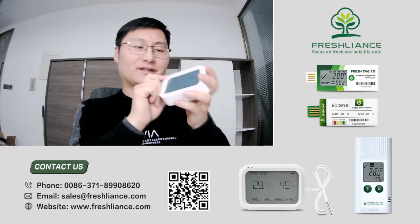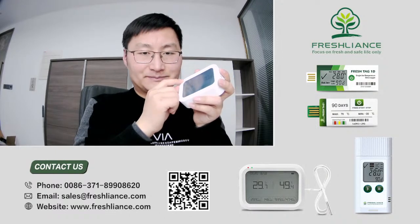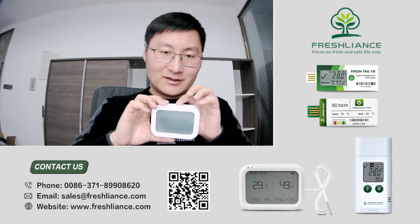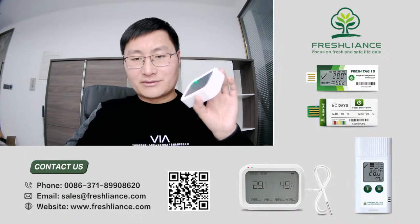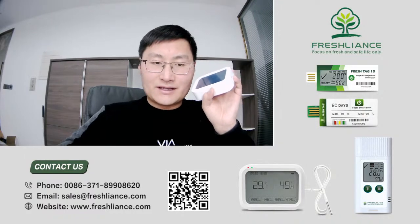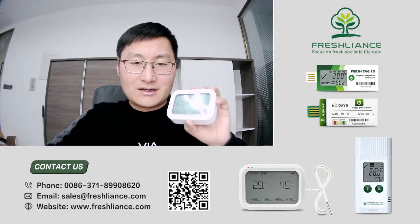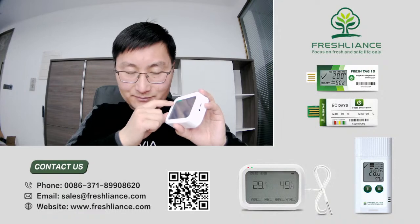And in normal working status, you will see the green light flash every 30 seconds. At alarm status, press the button shortly and the buzzer will be muted. And the LCD screen will show SOF, sound off. At this status, only the red LED flashes to indicate the alarm. If you press the button shortly again, the buzzer will give the audio alarm again. The screen will show SON.